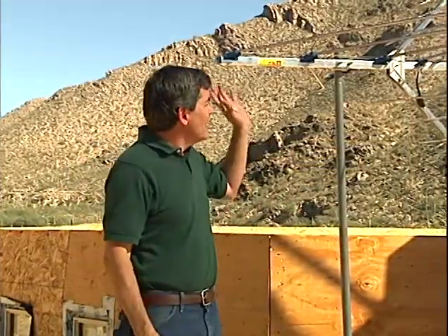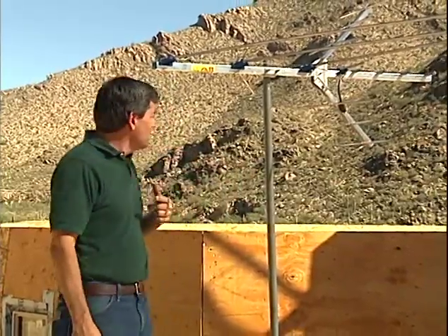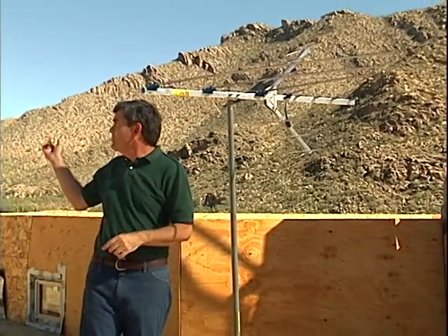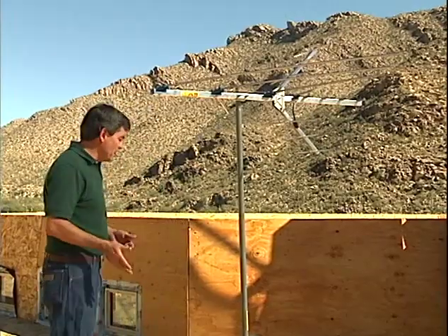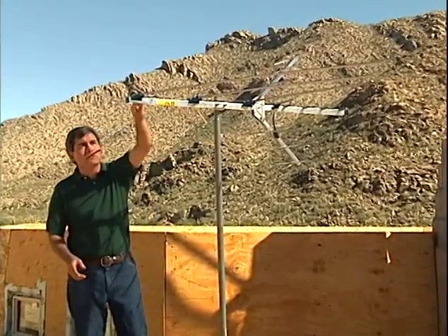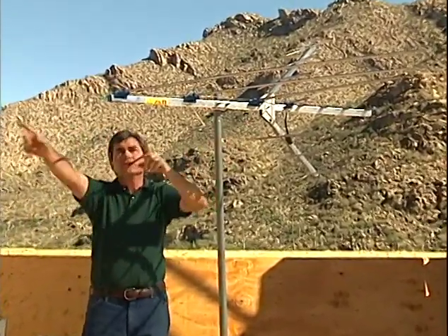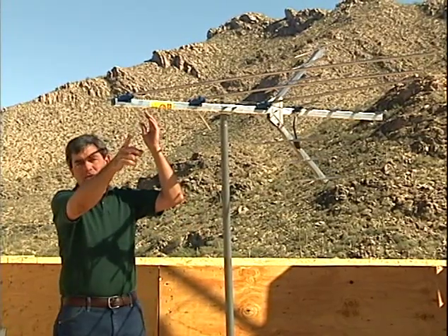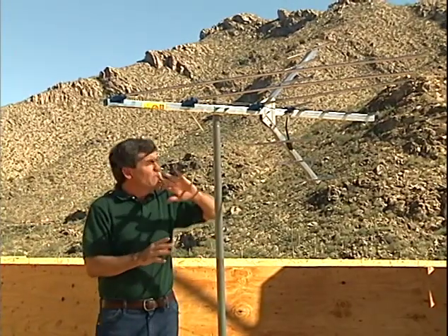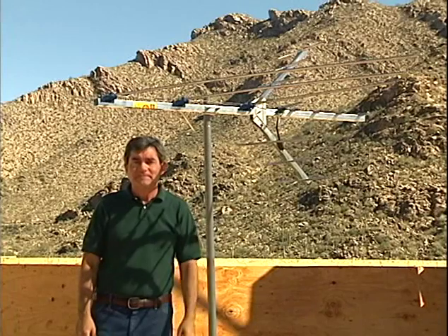Now, unidirectional Yagi antennas like this are definitely the antenna of choice in areas like this where there are high mountains or tall structures. This area would be a multipath nightmare. Now, it's also not intuitively obvious at all which way you point these antennas. You might think from the way these elements are mounted that you'd point the antenna in this direction. In fact, the only reliable rule of thumb is that the larger elements, called the reflectors, are in the back, and the smaller elements, called the directors, are in the direction that you want to point the antenna.